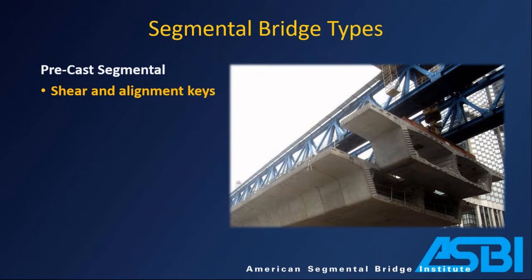That does have implications for design. It means you have to be a little bit more conservative in other places in the design of the bridge. Construction-wise, it means you have a lot more of these shear keys. You can see that the hardest working ones, the highest density of these keys, are along the webs to help transfer that shear. We also have a number along the top and bottom.